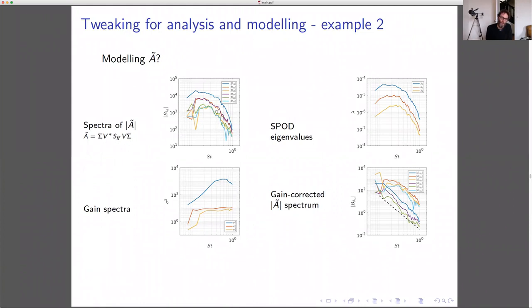And so we can factor that out of this to produce this picture on the bottom right, which is showing some kind of interesting frequency dependence. This is a Strouhal to the -3 trend. And it turns out that this persists over a range of Mach numbers. So this is showing some properties, empirical, of course, of this A tilde thing that might allow it to be useful as some kind of empirical model to follow changes in operating condition.